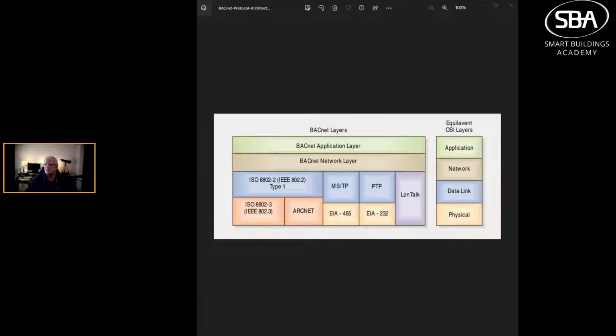The presentation layer, this is where the data is taken and formulated into viewable information. Oftentimes, this is when the raw BACnet IP data shifts into a viewable data format, whether it's ASCII or Unicode. And then the application layer. Here, programs run to visually represent and physically interact with the data from the previous layers. Typically, building automation systems use applications built around HTTP or SNMP protocols.